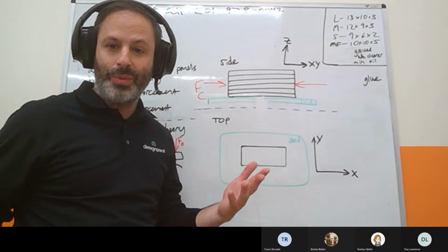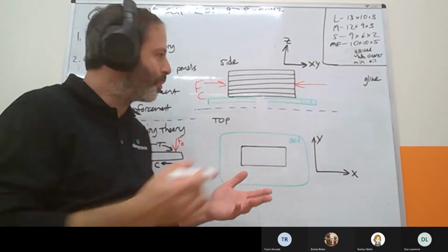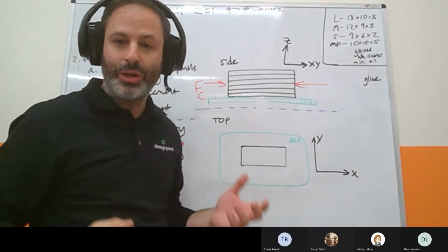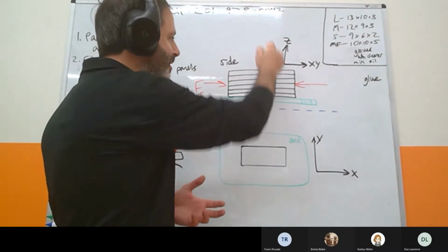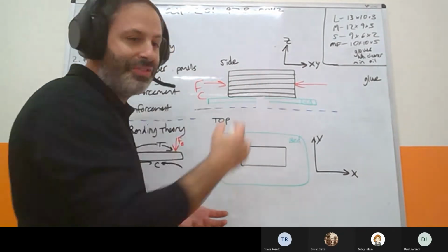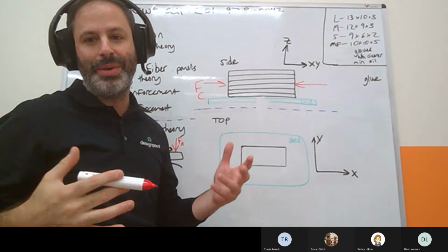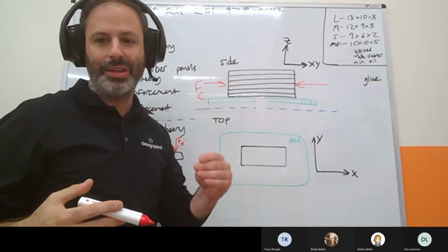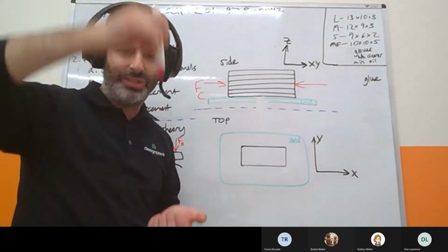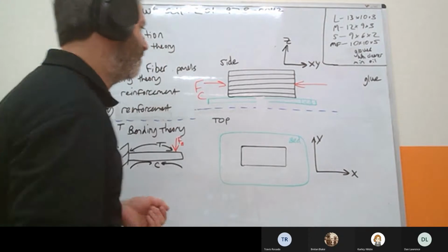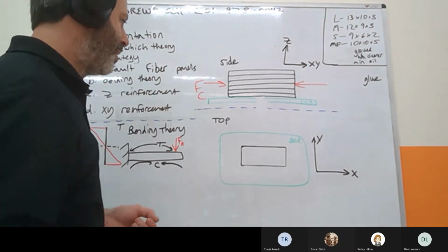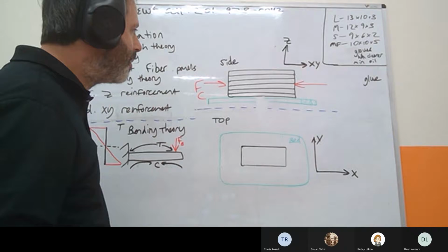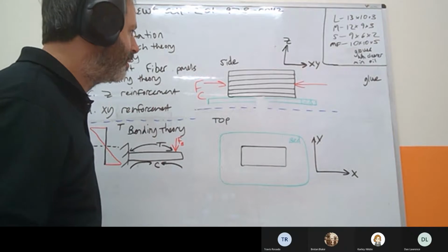And then really what I had said just before was if you really want to align your compressive forces along the z-axis, and then if you make it solid, that's really the best you're going to do. Make the part solid, no infill, align your compressive force in the Z, and that'll give you the best bang for your buck.